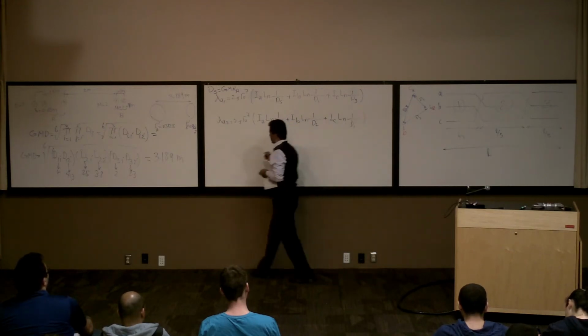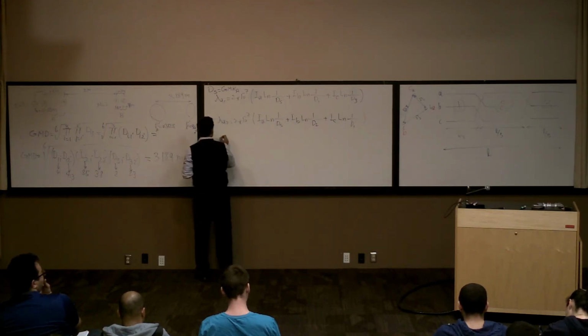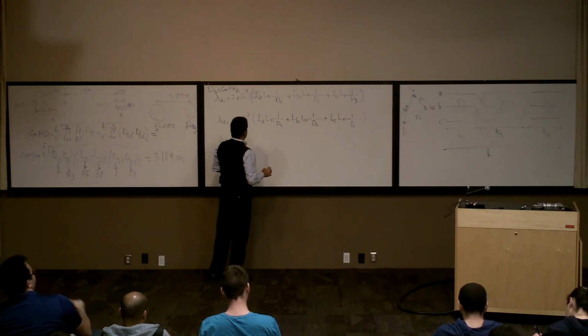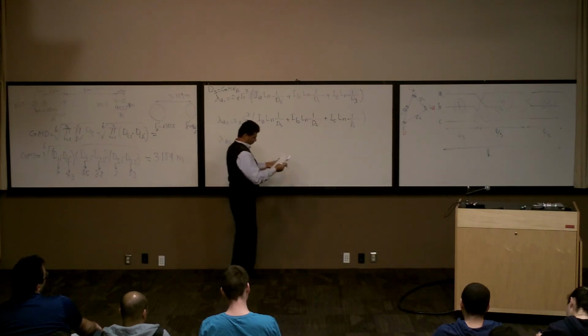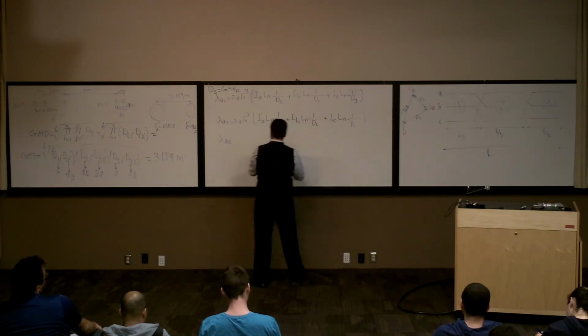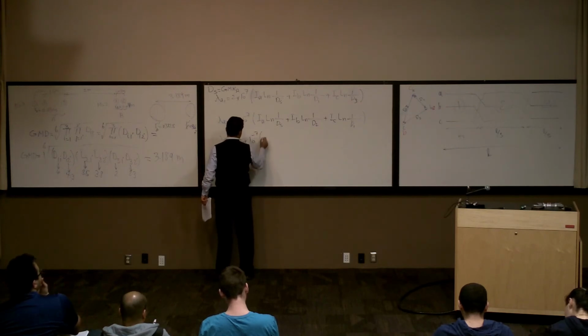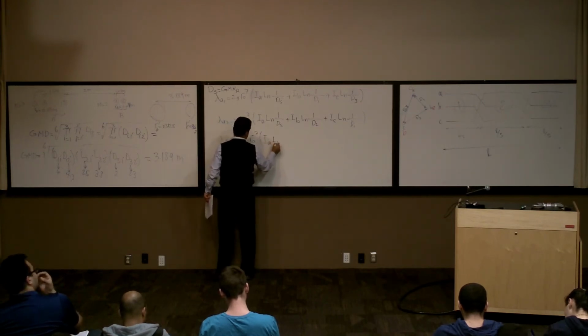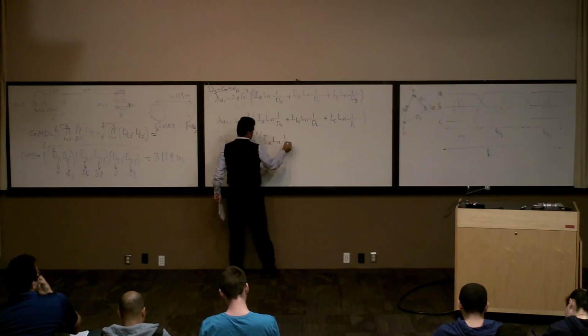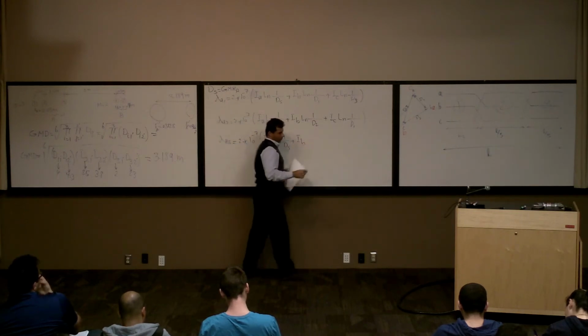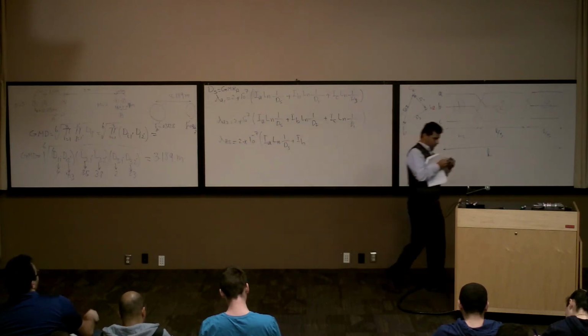Now let's go for the third one. Times L over 3 also. Lambda A3 is going to be 2 times 10 to the power of minus 7 IA ln of 1 over DS plus IB. Now I'm going to put it with the green color.